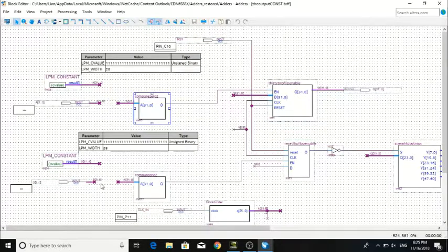On the other hand, if the last 4 bits of the address is 0001, the output from the compare 1 block will be 1, and this enables the resettable flip-flop. The resettable flip-flop stores the last bit of the data bus input.